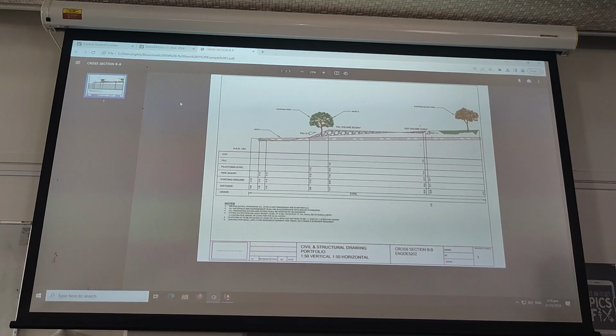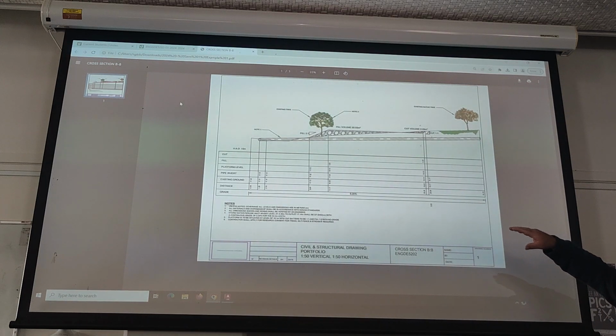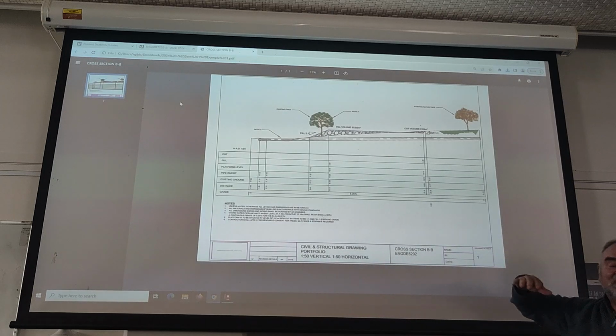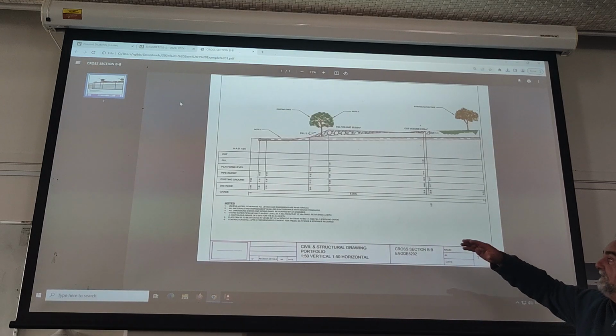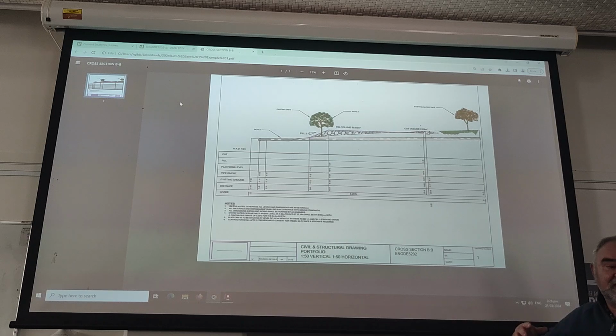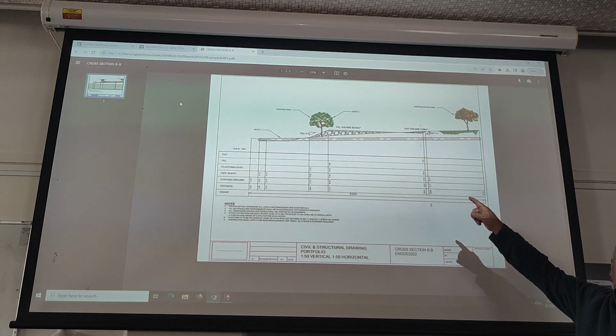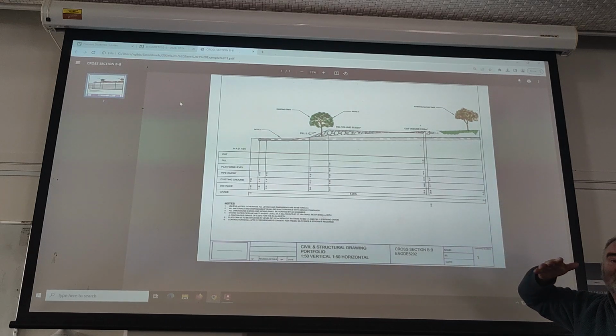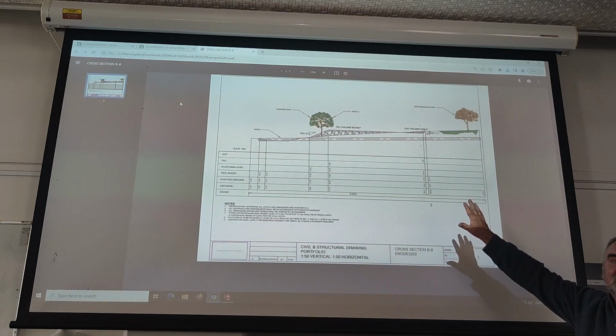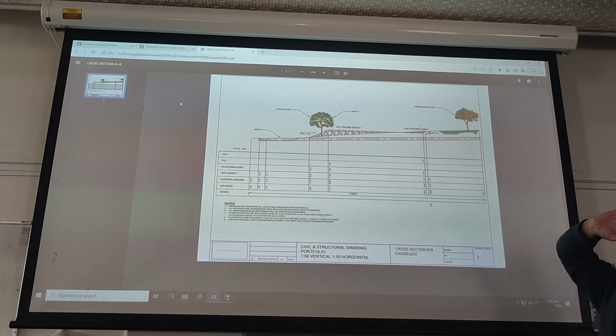The height is wrong. The grade of the pipe. No, actually, in that one, the pipe does go above the ground, so we actually have to put some more fill in. It's something that often happens with pipe work. The arrows are too big. They didn't adjust their dimensions for this one. They kept the old ones for the 1 to 100.